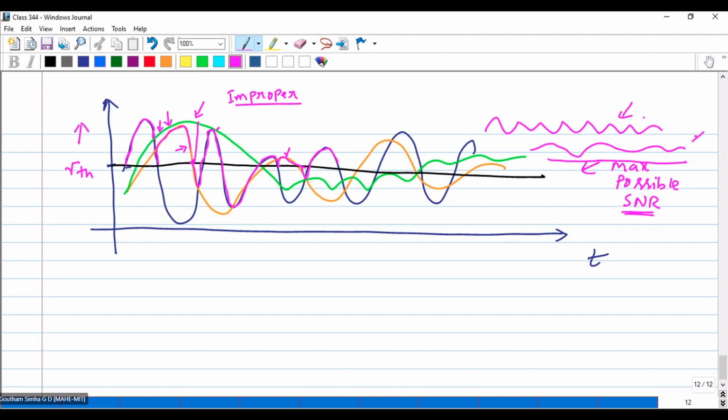This is a low complexity suboptimal alternative to your selection combining. Selection combining may not be optimal, but if you consider selection combining as the optimal detection scheme, then the switch and stay combining method, or switch and branch combining technique, becomes your low complexity suboptimal one. If you are getting a performance improvement of about 3 dB here, you will get approximately half of it, 1.5 dB, because this may reach lesser gamma threshold values.